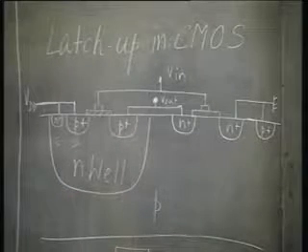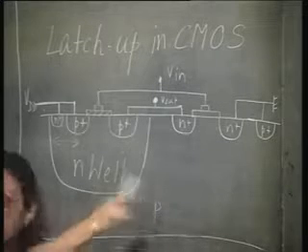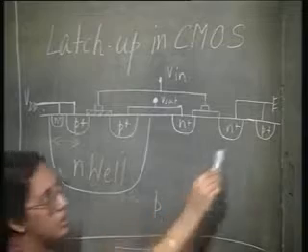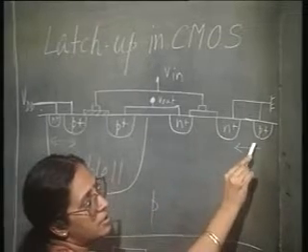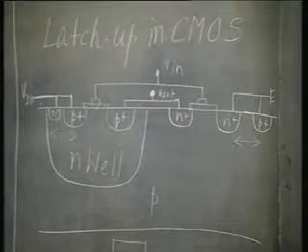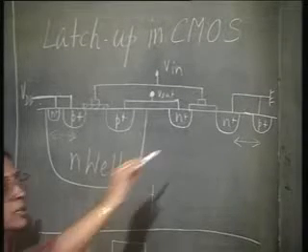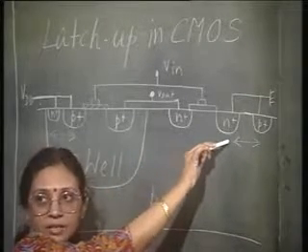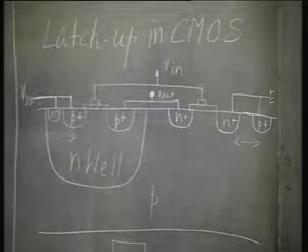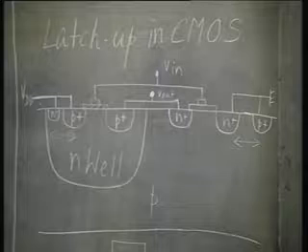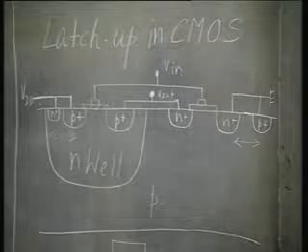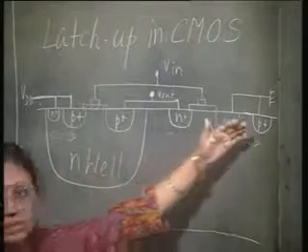Now, in doing so, again you see my substrate doping obviously is very low. So, again there is a possibility that here there is a sufficient potential drop, right. So, that this point here underneath the N plus source is at a potential of 0.7 volts higher than the ground potential. Holes are flowing in this direction, right?